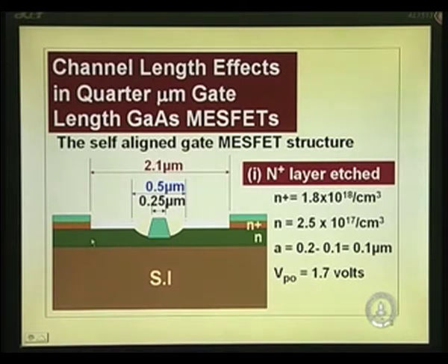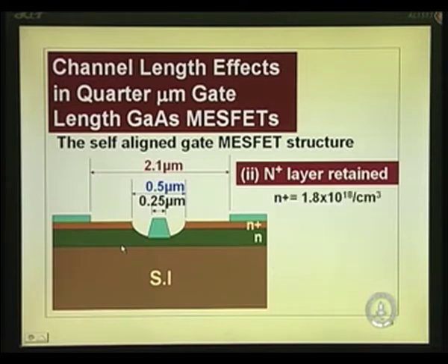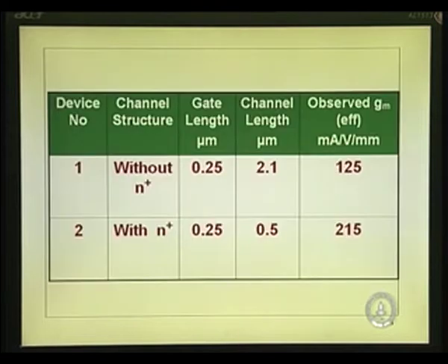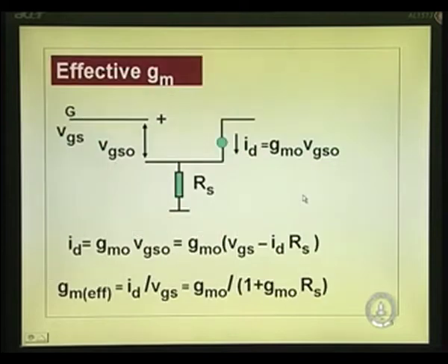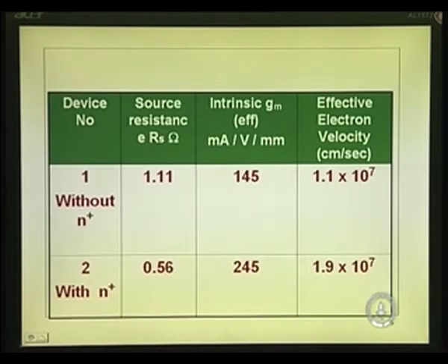The whole thing is the IR drop due to the current flowing. So, you measure the voltage drop and you measure the total drain current. The total voltage drop between these two divided by the current gives you the resistance between these two. That is the way they measured it, and then measured the GM effective also, and used that equation, GM0 is GM effective divided by 1 minus GM effective into RS, from this equivalent circuit, and you get the numbers.